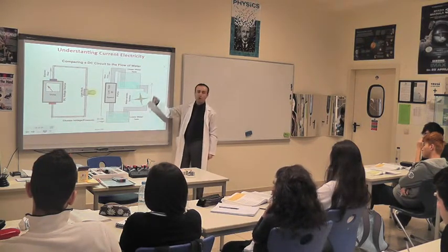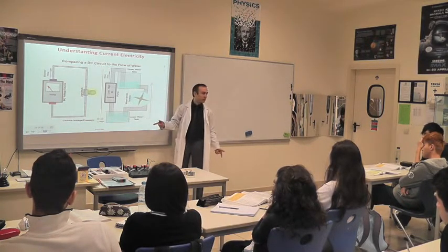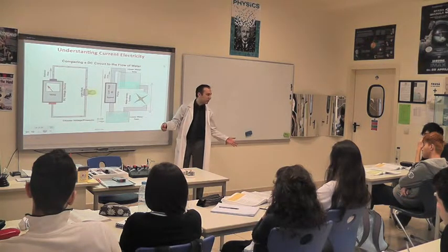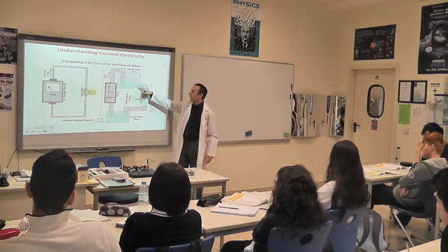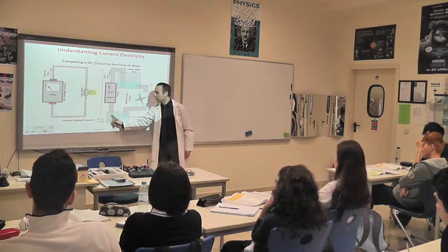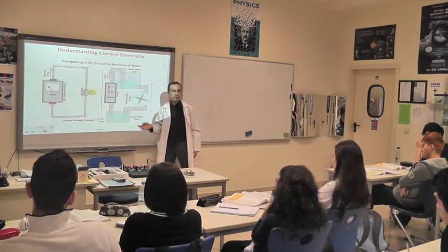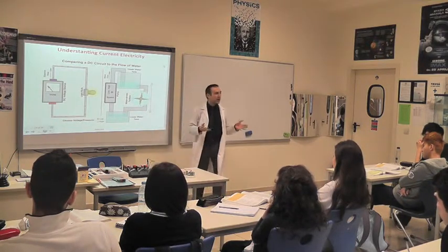This turbine gets its motion because of the movement of water, just like a windmill or a turbine of a power station, same method. The pump pushes the water up, water turns the turbine and goes back to the lower tank, and then the cycle repeats itself.